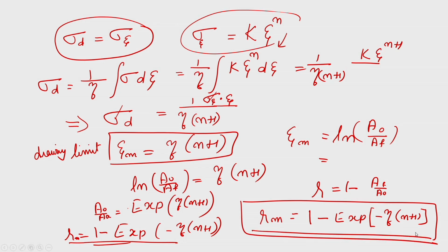Okay. Now, when you are having a repeated reduction through a series of dies, the n will keep on decreasing, because even though you are having repeated deformation, the strain keeps on decreasing and work hardening keeps on decreasing. This is the general nature of the material. So, if you look at the work hardening rate versus strain, you will find that it decreases. Initially, you have a very high work hardening rate, but with the increase in the strain, it will just saturate off. So, it will keep on decreasing and then it will remain constant.